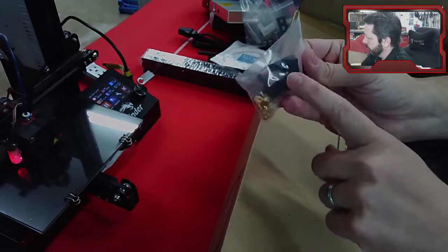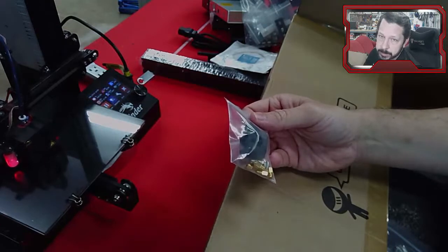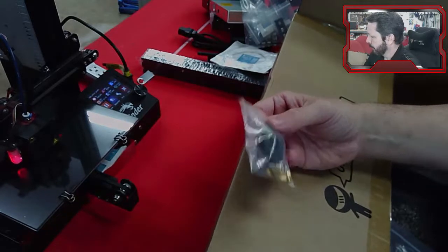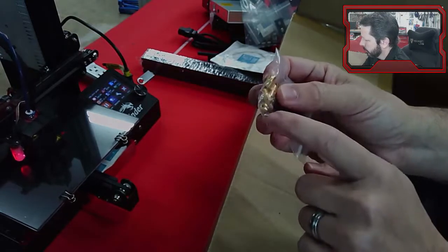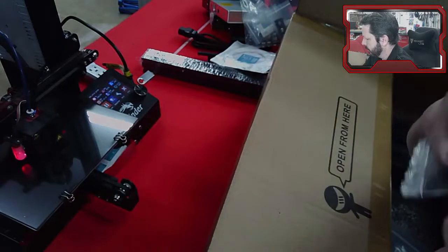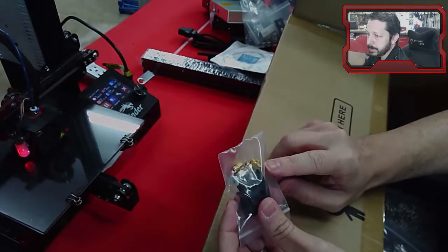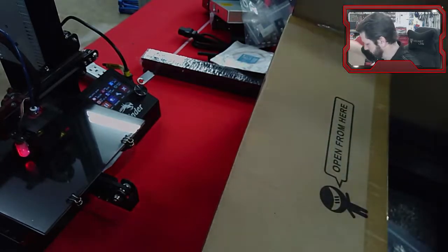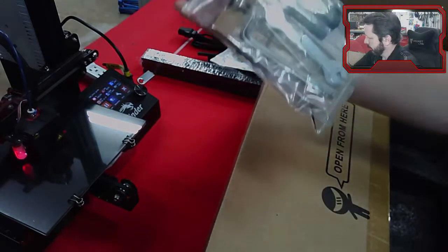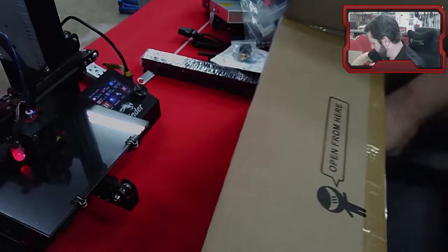Some hot end socks. So these are silicone socks that will cover the hot end, one, to protect you, and two, to keep its temperature more stable. And you've got some replacement nozzles, four little brass nozzles there. I assume they're all the same size. Normally they're stamped on there, but I don't see anything that says what size these are. But by default, if it doesn't say, you can assume they're 0.4 millimeter nozzle diameters. A whole bag of screws and zip ties, a couple of stamp tools and stuff like that. All right, anything else? No.